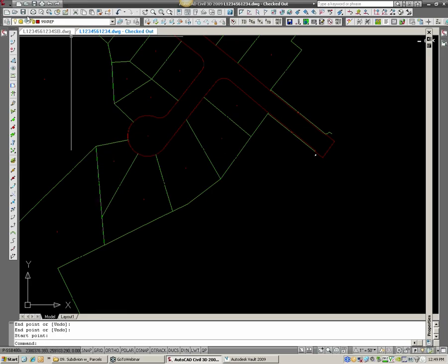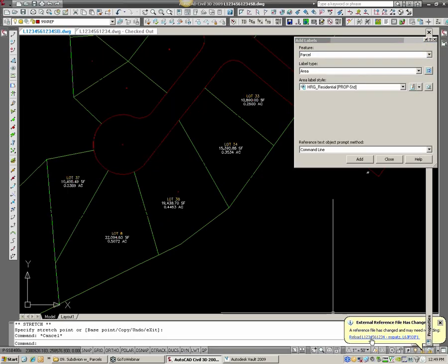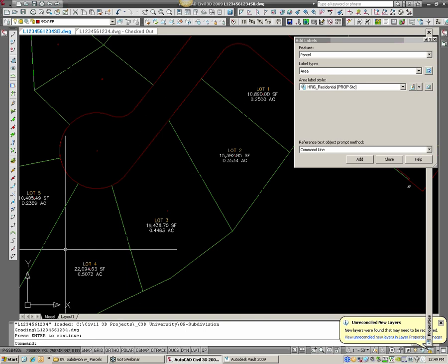And you don't see anything in this drawing, right? But if I hit Save, and I go back to my other drawing, get my XREF update dialog, and you can see all the parcel numbers renumber themselves going down through here. Okay?